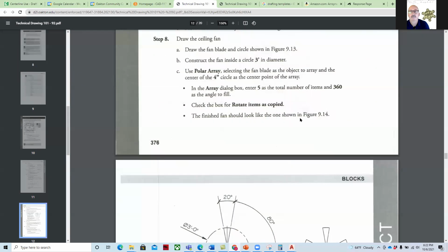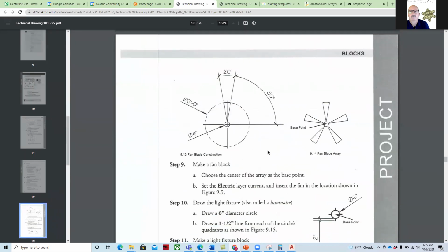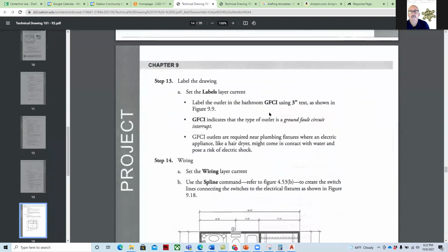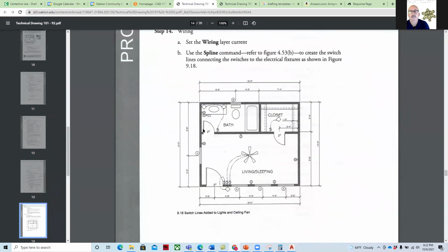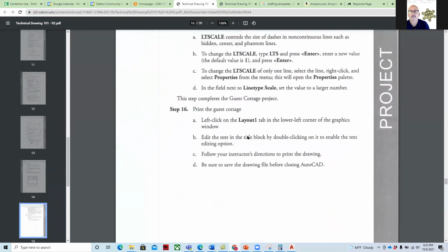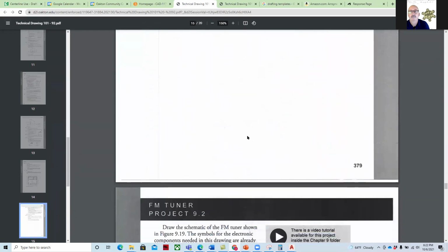Yes, you can find blocks on the internet that are already created, but our job is to go through and create these different standards. So we'll create these standards, place the drawings with the blocks, place the plumbing on the plumbing layers and the electrical on the electrical layers, and then put the drawing on the B-size architectural title block.